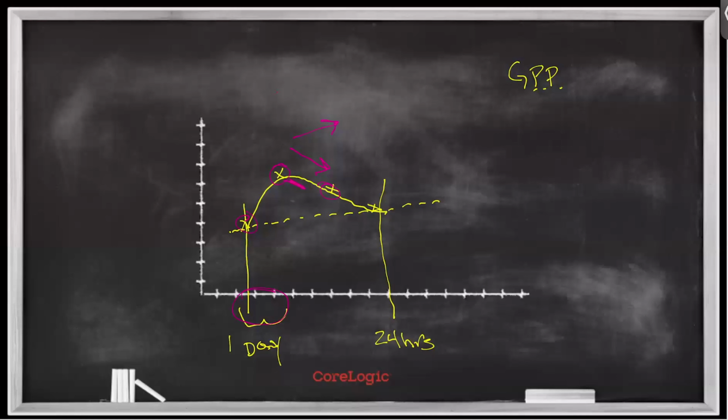The longer it takes you to get that bulk free water, that water that makes materials feel damp to the touch, the longer it takes you to rid the materials of that moisture, the wetter those assemblies are getting because you have absorption that is occurring into those materials simultaneously, right? Because water moves in every direction. So leaving that environment with a high humidity ends up creating a much wetter project, wetter materials that are going to take much longer to dry. So that's the other reason why this is so critical.